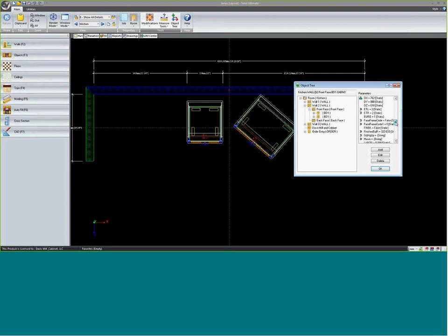So if I look at my DX, 762, that's the width of this cabinet, 762 millimeters. DY is 880, which is my height. The DZ is 610, which is the depth. If you look at the X, Y, and Z parameters, this is in relation, up one step of the tree, to the front face of wall number 2, right? So the cabinet's origin point is 2,004 millimeters away from the origin point of this wall. In Y it's 0 and in Z it's 0 because it's on the ground and it's touching the wall.